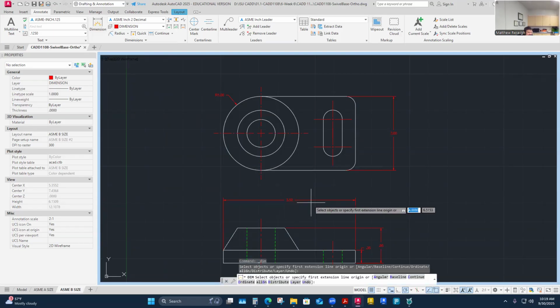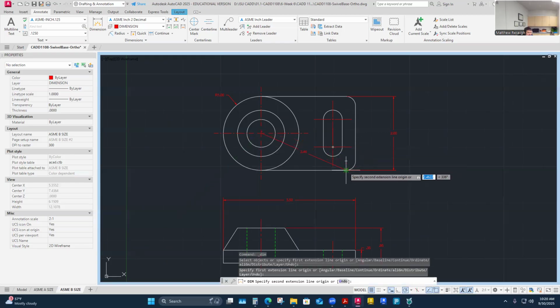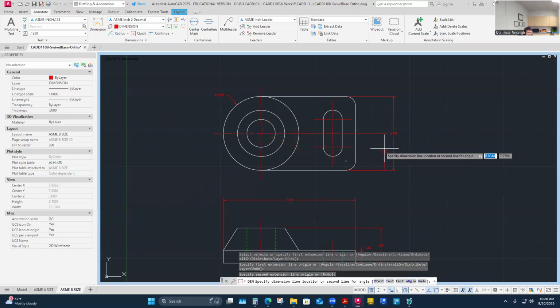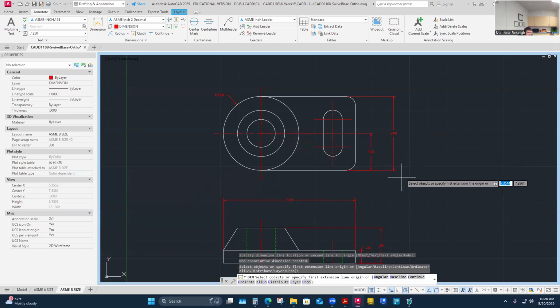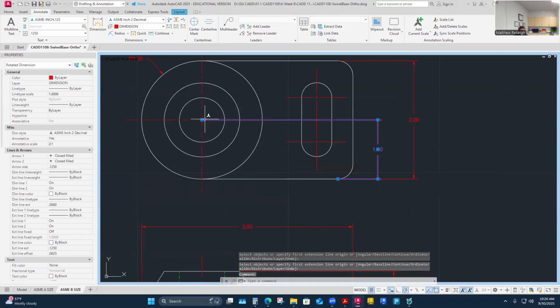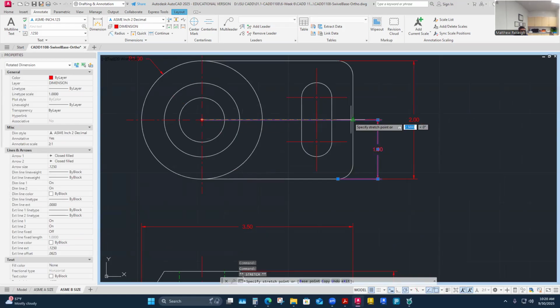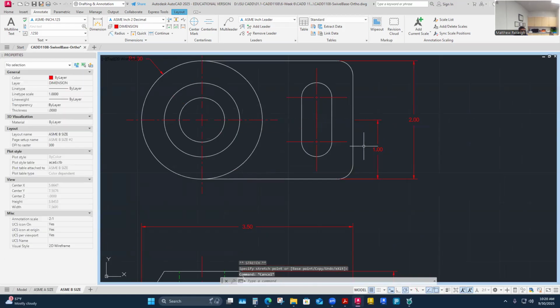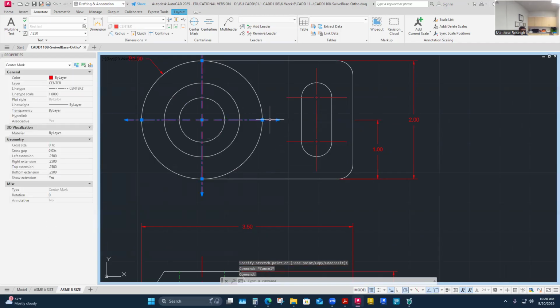Thinking of the base plate still, I might say, well, from this front edge to the center of the plate, maybe this is a good locating dimension, right? It's off a center line. It's right here. This is 1 inch. It's really the plate that I'm thinking of locating in the Y direction, of how this part sits.